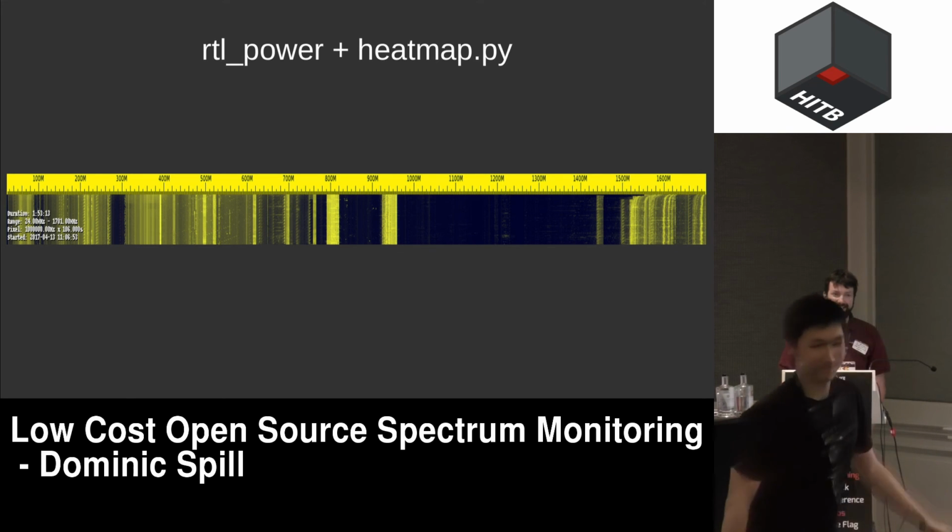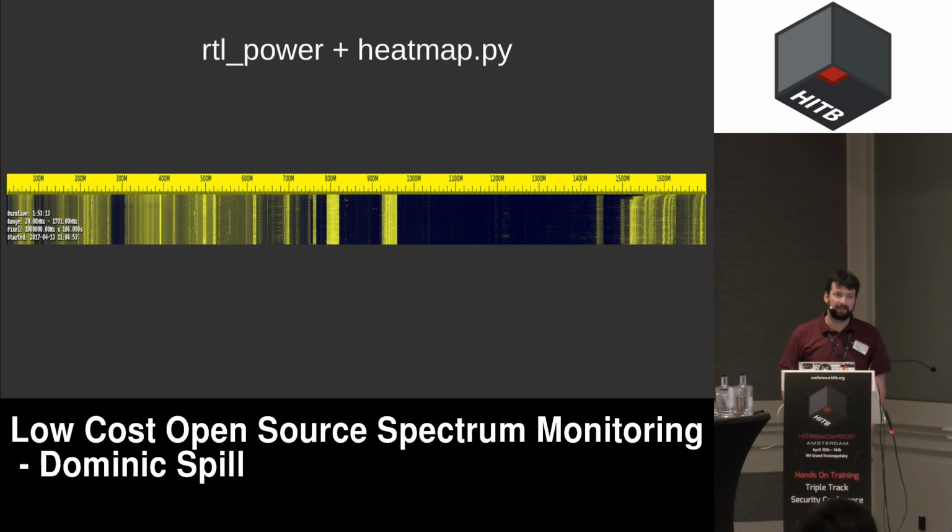Yeah, Mark. So I'm just curious, when the HackRF is sweeping, what's the duty cycle at any one given frequency that it would see? So what we do is, we can increase the duty cycle based on how much data we want to capture, but reasonably what we do is we tune to a frequency. We're pulling back data at 40 megahertz. Let me try that again. We're pulling back data at 480 megabits normally, and that is made up of 16K buffers. So if you can do the maths to work out how long a buffer lasts, what we do is we tune, we wait for 2 buffers in length, which is a very short time, in order to allow the tuning to settle, and then we just capture one buffer, and we're literally operating on the last n number of samples of that buffer, and the n in that case is the width of our FFT. Yeah, thank you. No worries.